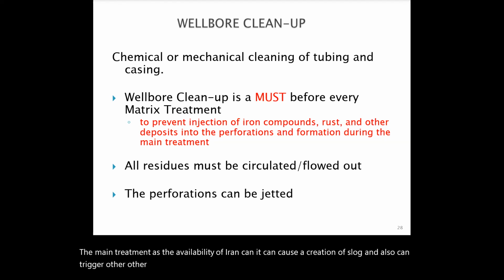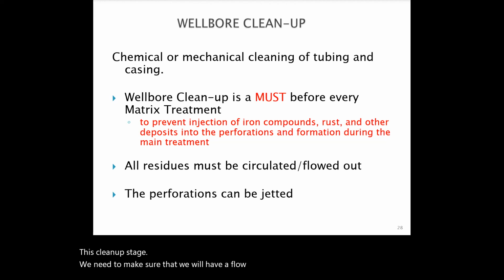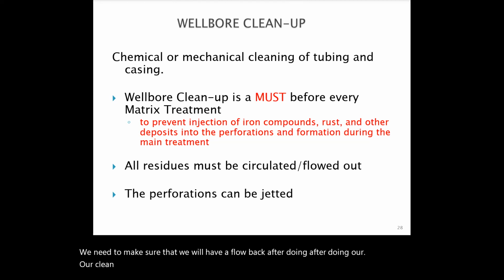Using this cleanup stage, we need to make sure that we will have a flowback after doing our cleanout, and also we need to jet our perforation. So that's why this is an important step in our acidizing.